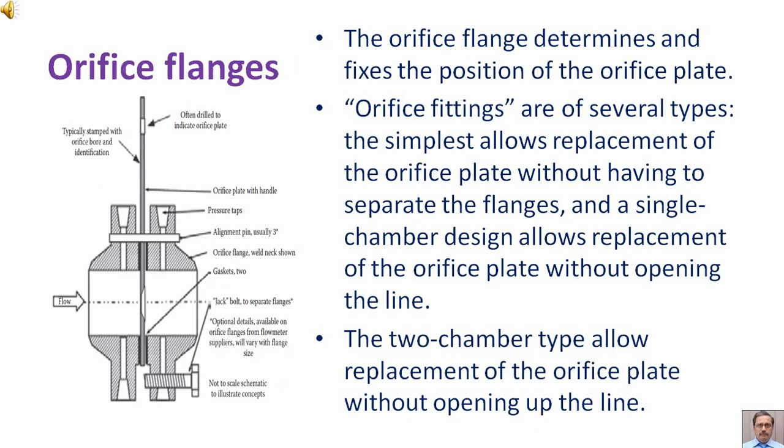Orifice flanges. The orifice flange determines and fixes the position of the orifice plate. Orifice fittings are of several types. The simplest allows replacement of the orifice plate without having to separate the flanges, and a single chamber design allows replacement of the orifice plate without opening the line.